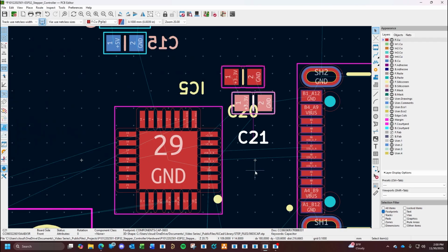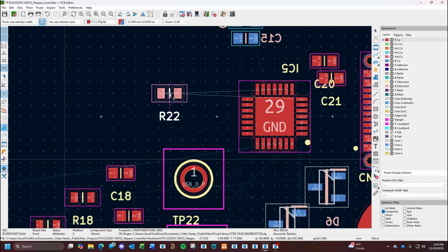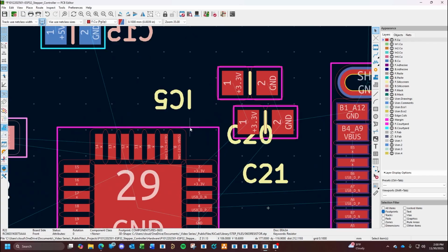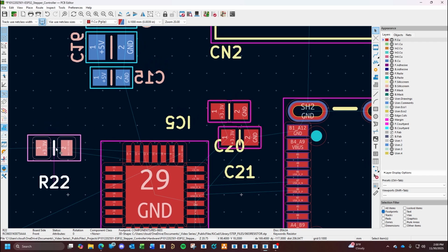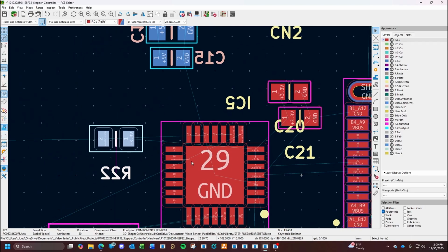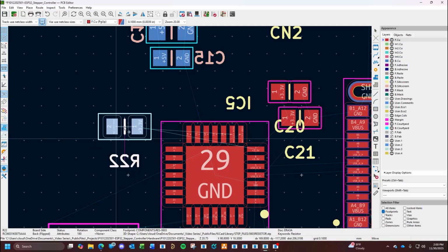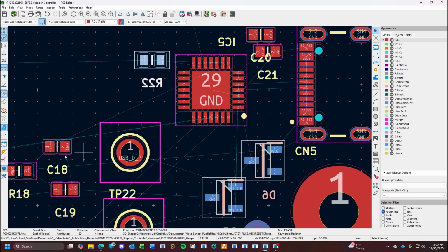Okay, that's kind of fine. That's reset, so that's a different circuit that we can actually throw on the bottom. Not directly under, because we're going to have vias in here to tie into the ground plane and things like that. So I'm not terribly worried about that right now. We'll figure out that guy to go on the bottom. These will stay on top to be close to the actual supply pins.